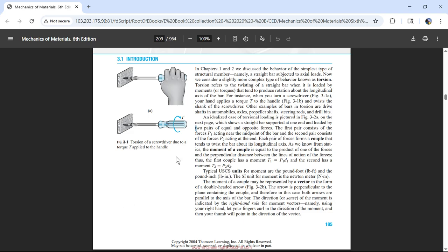And if you're working in that linear range, you get plenty of strength in that linear range. You hardly get too much extra strength, and the extra strength that you are getting has to come with deformation. If a material is being stretched in the linear range, you also have this very magical property that when you stretch that bar and then let go, all the molecules go back to the original location. And so that's very fascinating.